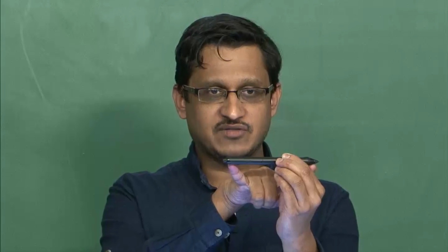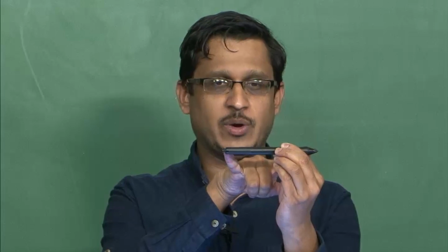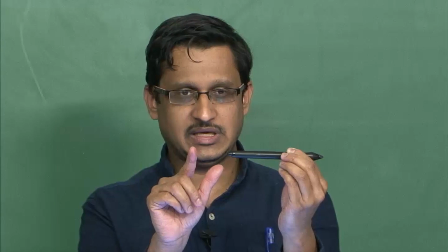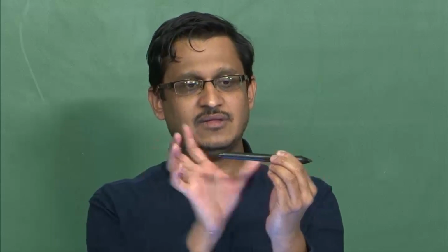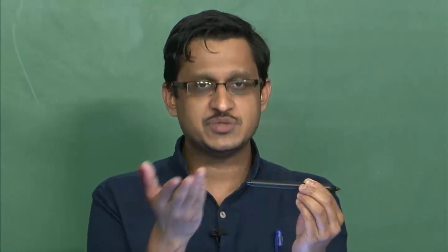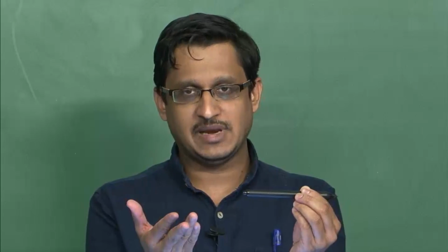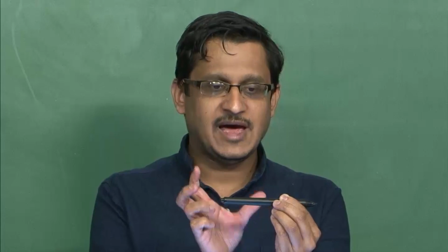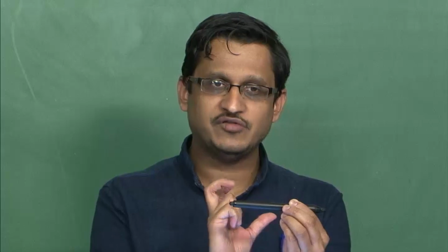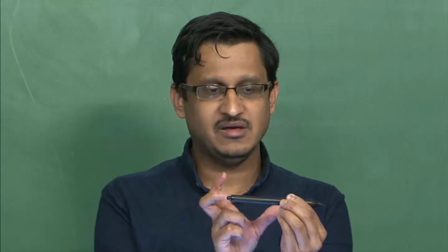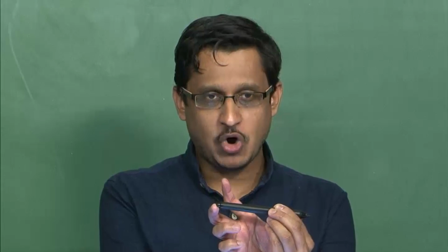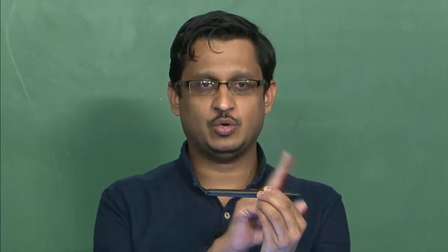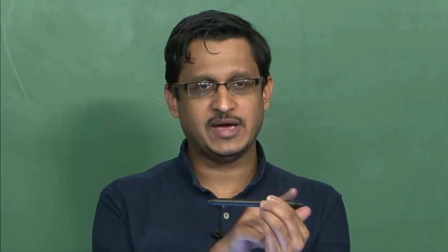But this wire which I have connected, which is the interconnect that I am talking about, if the voltage change is immediately available at the input end of the next IC, then this wire can be treated as a wire because it has not introduced any delay, it has not changed the shape of the pulse that is being transmitted. So, as long as the delay introduced by this piece of wire is very small compared to the rise time of the change of the state of the voltage source that is connected to one end, then we usually do not consider the wire as a transmission line.